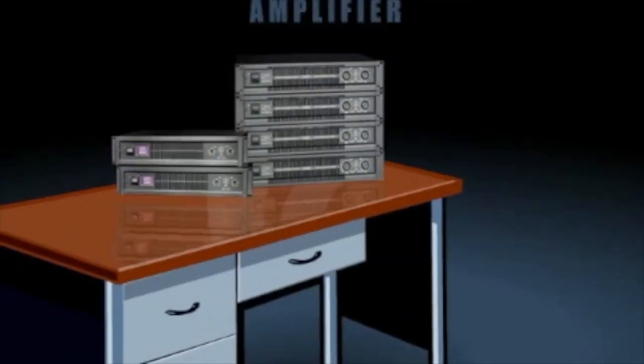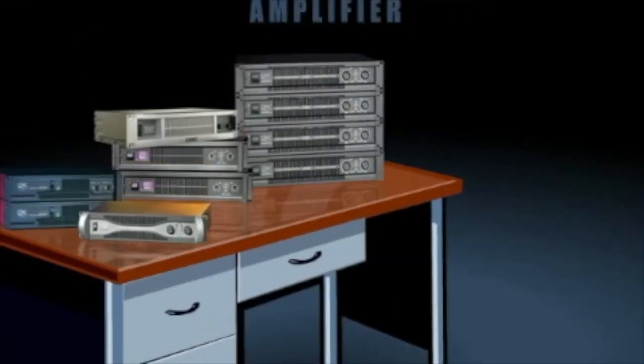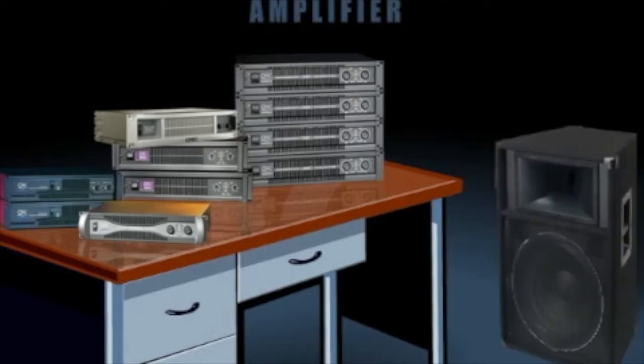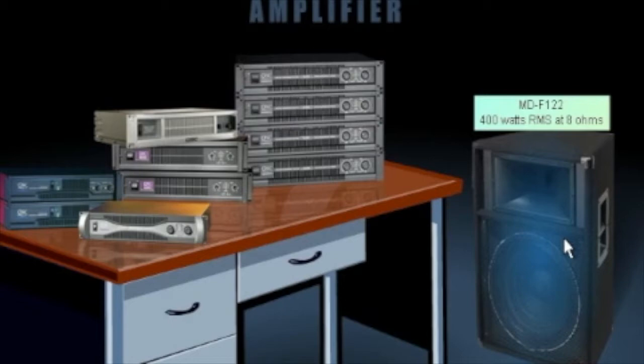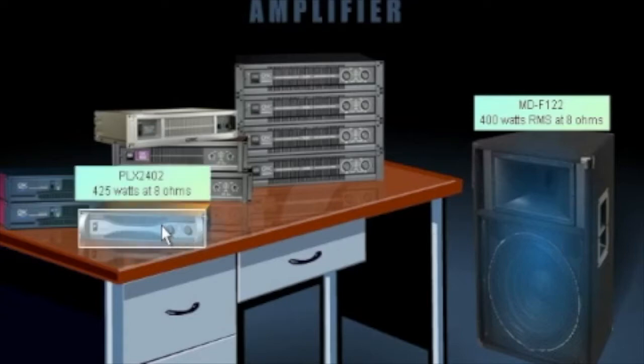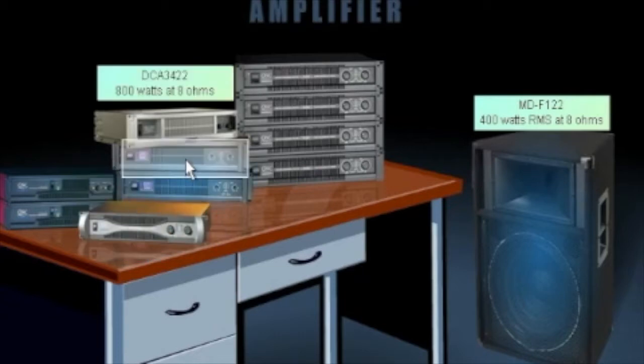The process of selecting an amplifier begins by determining the power handling of the loudspeaker you want to drive. In the case of an MD-F122 loudspeaker, 400 watts RMS at 8 ohms. Naturally, one would select a 400-watt amplifier to power this loudspeaker, but this is not necessarily correct. In reality, you would want to use an amplifier that will produce up to 800 watts at 8 ohms, which would provide 3 dB of headroom.